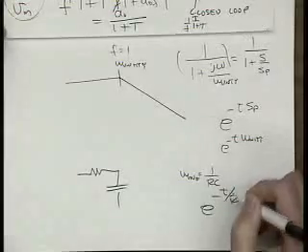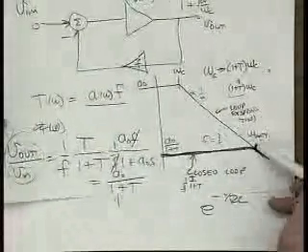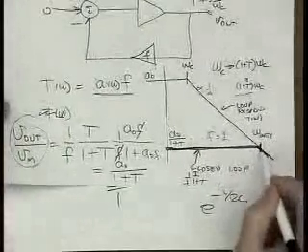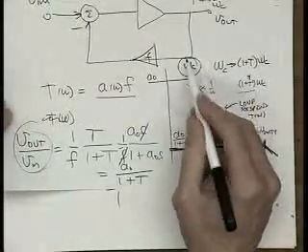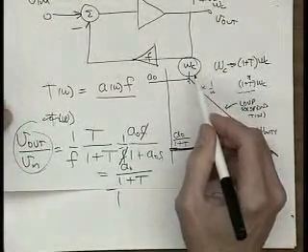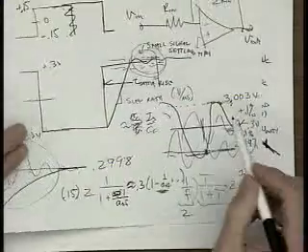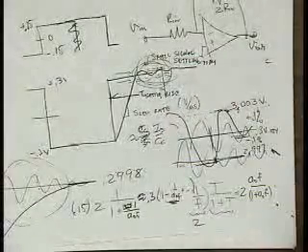So what this says is that you want to keep the closed loop response of this amplifier, which is related to its compensation pole, as high as possible. This settling here is related to the bandwidth of the amplifier I'm trying to get to.